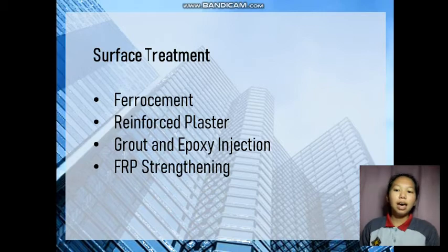So the FRP can enhance shear, flexural, compression capacity and ductility of the deficient members. Glass fibers are most common types of fibers used as the majority of commercially available FRPs. FRP system is commonly used for structural applications.